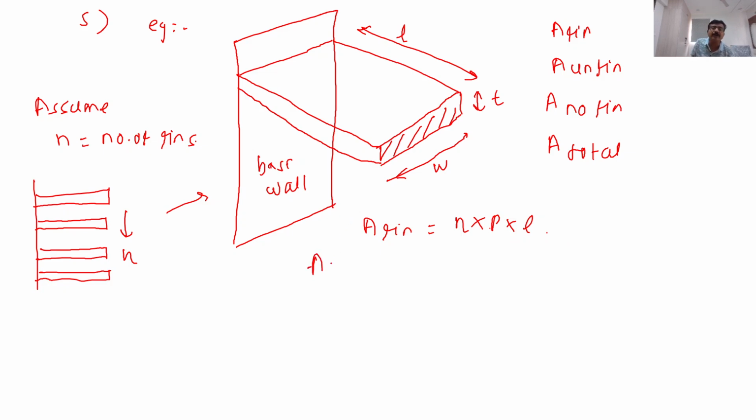Now what is A unfin? A unfin is nothing but the area of the base wall. Remember, I will write here, area of base wall. It is nothing to do with fin area. It is area of base wall where the fins are not attached.